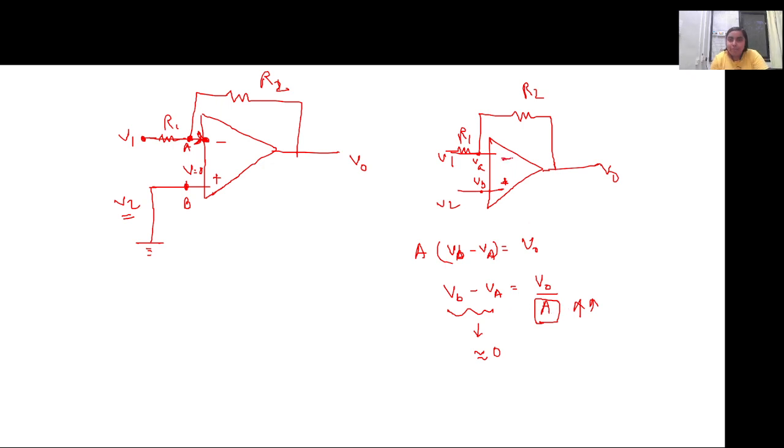So in our tutorial we won't find a condition of non-ideal case, but if there is a non-ideal case, we will have to calculate V0 based on that. If the op-amp is non-ideal, this gain value either shall be given, or there will be conditions where we will be able to find this VA and VB. This thing you have to remember.